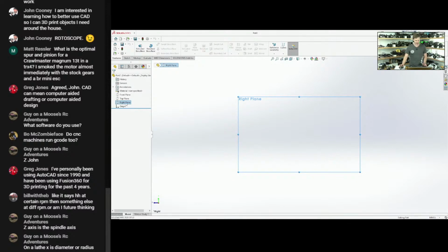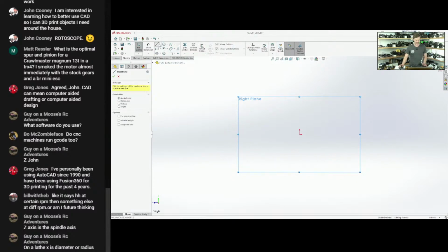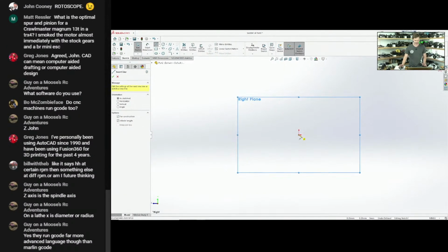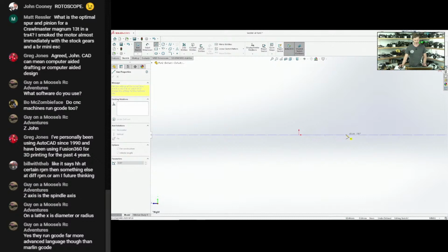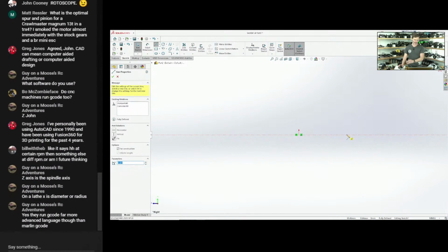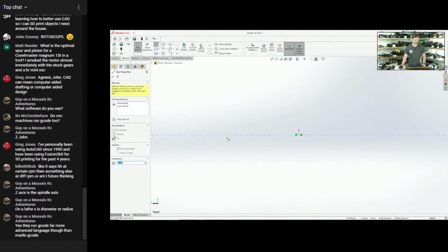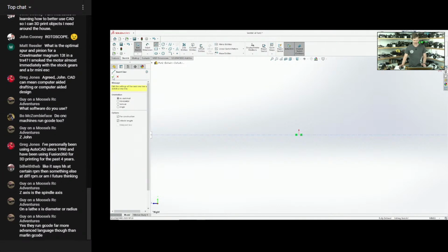This is going to be a motor housing. So on the right plane, we're going to start with a sketch of a line, and it's going to be a construction line of infinite length in SolidWorks. I'm going to go from that origin and just move it out sideways. This gives us an orientation line to revolve around. There we go, we got the line.